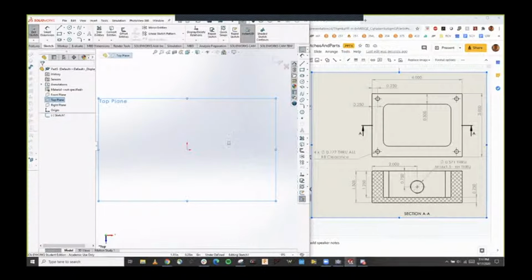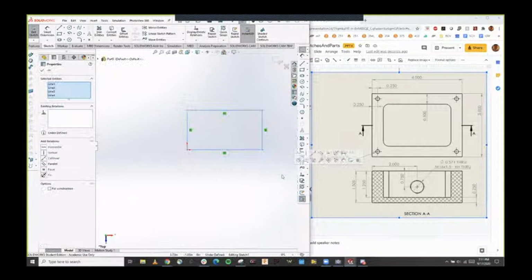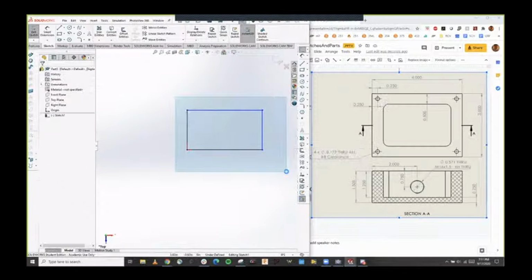Now I'm going to try something new with this method where instead of making a rectangular box like this, I'm thinking about how I am going to create these holes. The easiest way to create these holes is with mirrors. Essentially, if you have an axis through the middle of these 2 points, you can mirror these holes over so you can define one at once and then copy it. Thinking about that, what's the easiest way to make it so that I can mirror things? That is to have the origin in the middle.